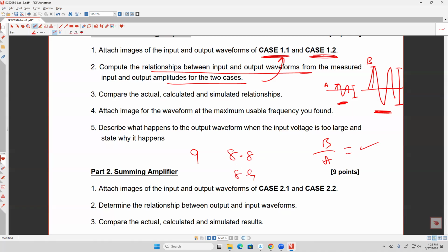Just use the ohmmeter and make sure your resistors are correct. Because if you put in a wrong resistor, results are wrong, and we don't know the reason. You will check everything. Let's check this one, let's check this one. So just to avoid mistakes, once you go, use the ohmmeter. Make sure the values of the resistors are correct before using them.